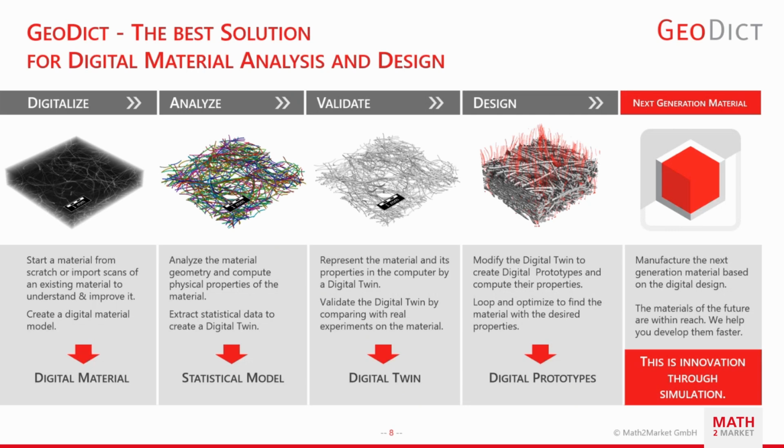Some similar process for non-woven materials. Of course, we also start here very often with micro-CT scans, and we will also show an example later of what you can do when you only have 2D data available of your non-woven. Also for non-woven, we can analyze the fibers, of course, for all the properties that could be relevant here. And as we will see in a very interesting talk tomorrow, you can also use this input from the CT and from FiberFind AI and export that directly to other software such as Abaqus.